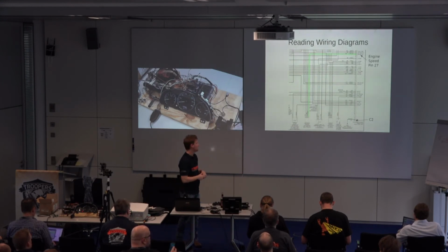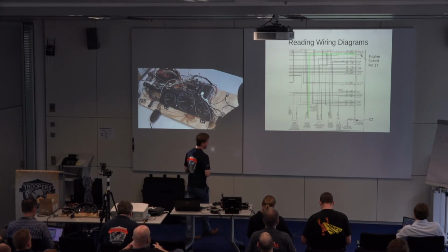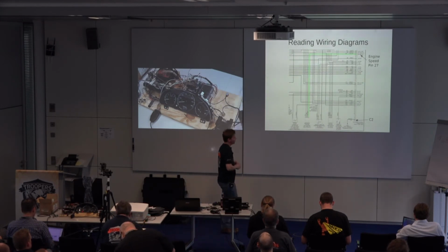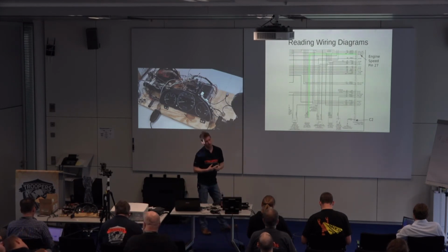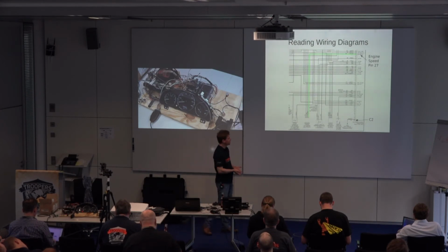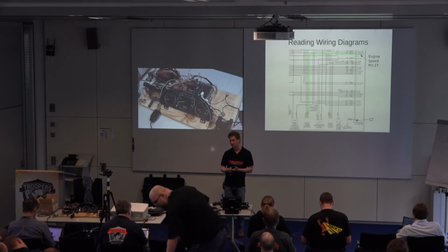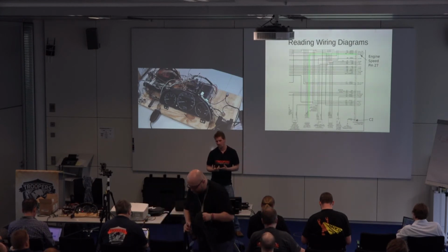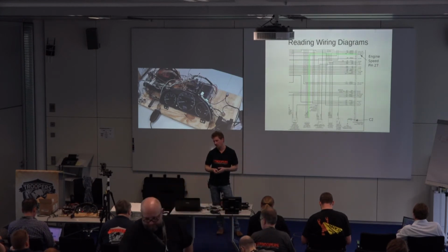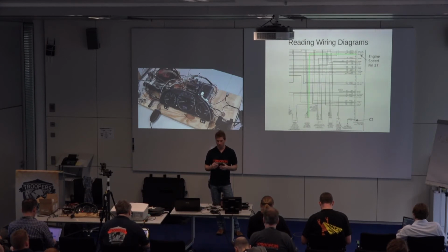And so like here is what they kind of look like. So they're different than a schematic if you're looking at normal schematics. They're broken down into their functionality. And once you get used to them, they're pretty nice. So there'll be a whole, like maybe 5 sheets on just your power, and there'll be a bunch on ground. And to get your initial unit up and running, that's the first one you're going to start with. To figure out, there are going to be like 12 volts coming out. Which ones does it plug into for your ECU?